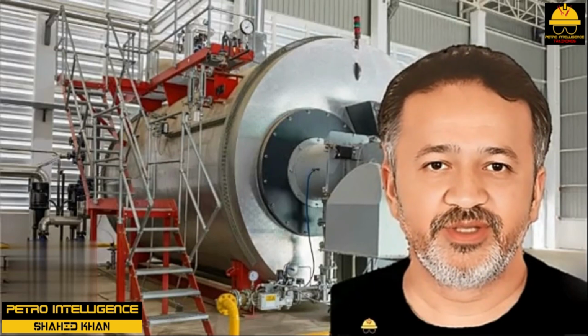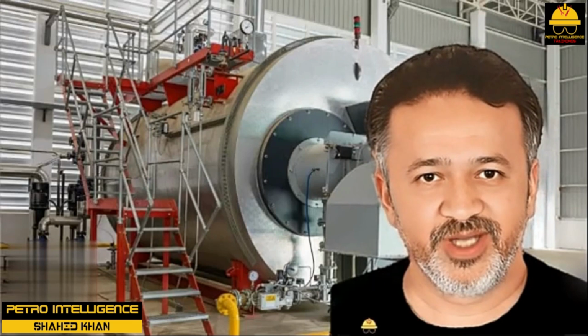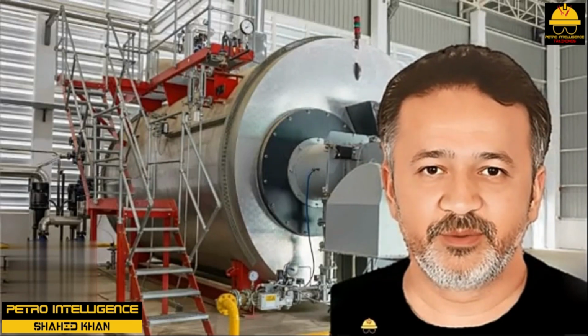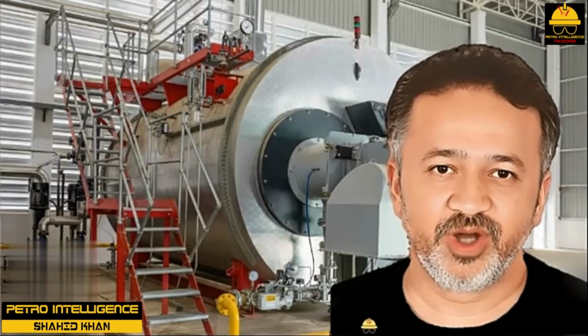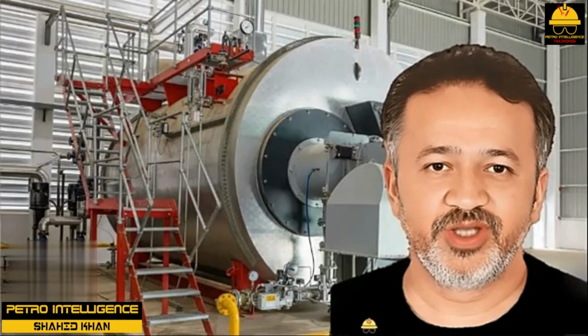The lower the pressure in the surface condenser, the greater the amount of work that can be extracted from each pound of steam. Discounting the presence of air leaks, the temperature inside the surface condenser determines the pressure of the steam exhausting from the turbine. This pressure is the vapor pressure of water at the surface condenser outlet temperature.